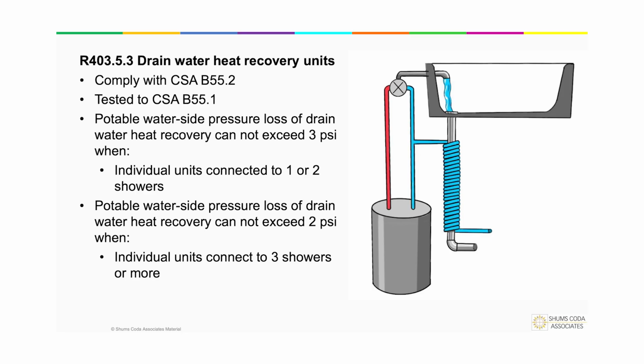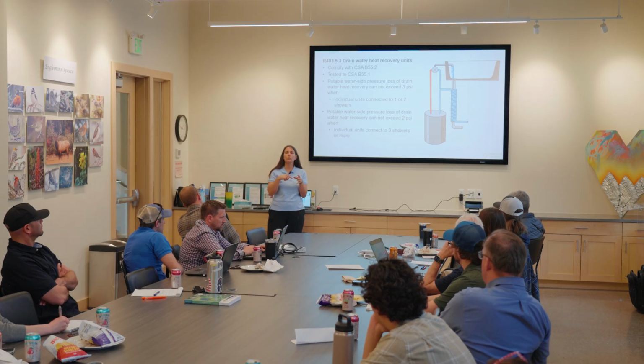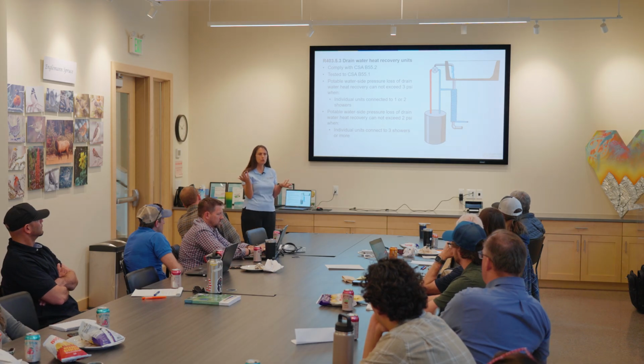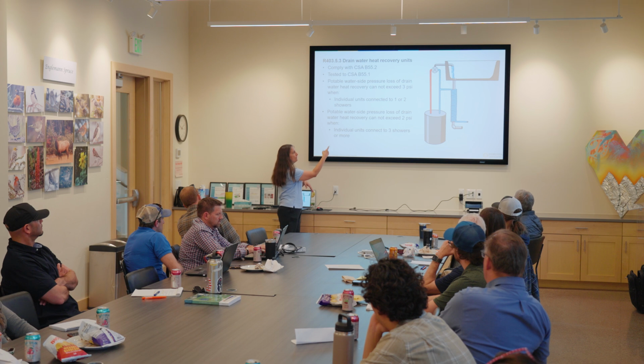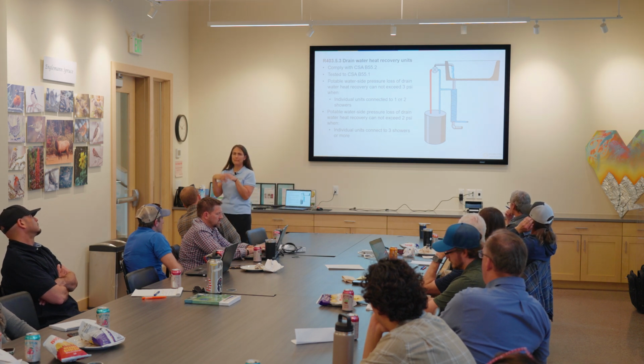So prior to the water going into whatever is going to heat the water, you have the opportunity to take the heat from your shower. You can make that hot water shower work for you. What it does is it preheats the water before it goes into whatever is going to heat your water, because it takes all the heat from the waste drain and preconditions the...